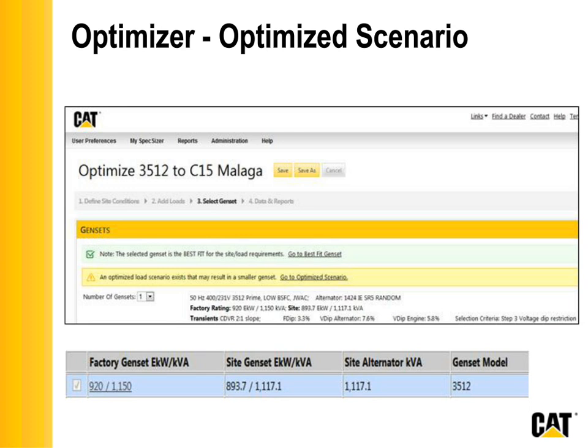And so many times, working many, many inquiries over the years, I would see that if the user of the tool had just run the Wizard, they could have downsized their genset, the kW or the kVA, or the rating. So what we did for SpecSizer Web is we automated the Wizard, and we call it the optimizer. We run the optimizer in the background all the time.